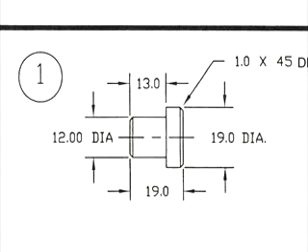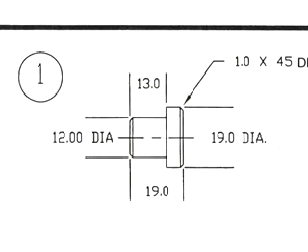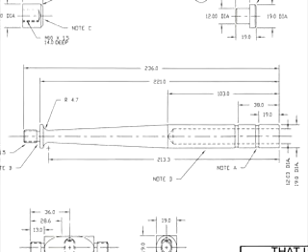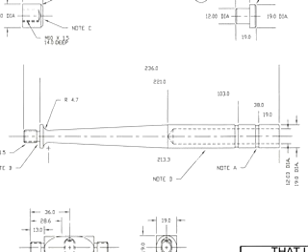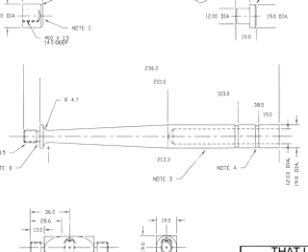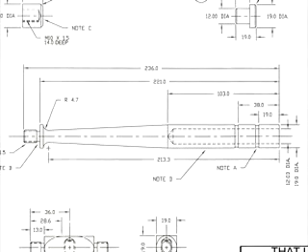Removing the dimension lines from the drawing of a small part doesn't confuse things that much. That's mainly because the dimensions are quite close to the extension lines already. However, on a larger part or on a looser drawing, our dimension lines can really help to clear things up, as we can see with this hammer handle example.